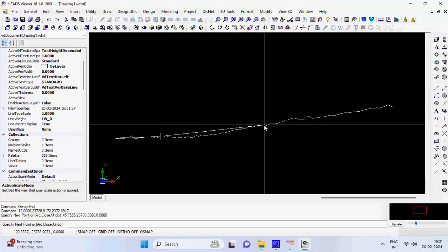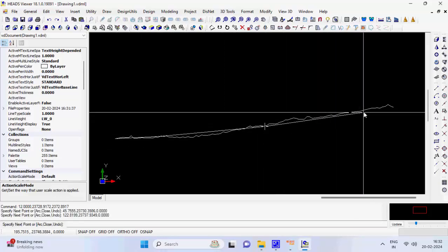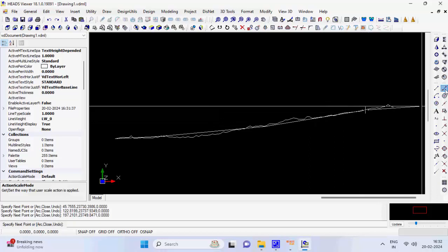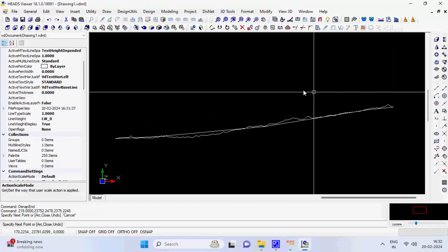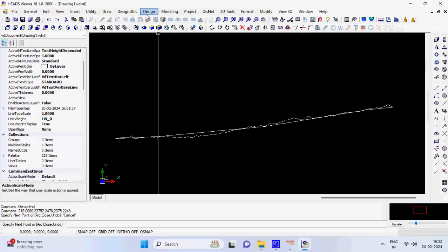Step 64. The design dialog box comes. User may change the data as desired. The polyline should pass as close as possible to the ground long section. The points should be sufficiently away from each other to accommodate curves to be set at this point. Step 65. If any message comes for large curve, the vertical curve length, VCL, is to be reduced, and again click on Apply.